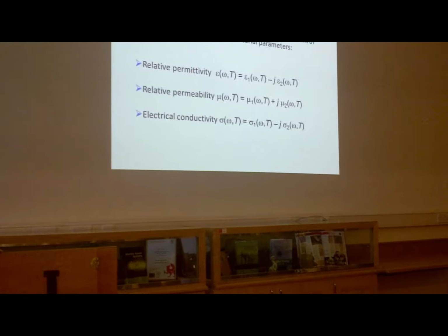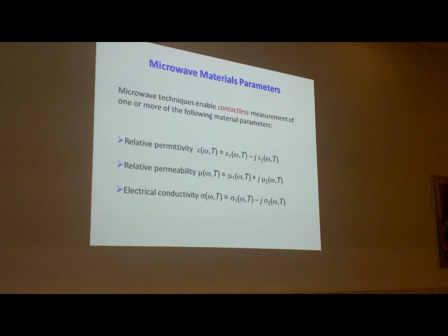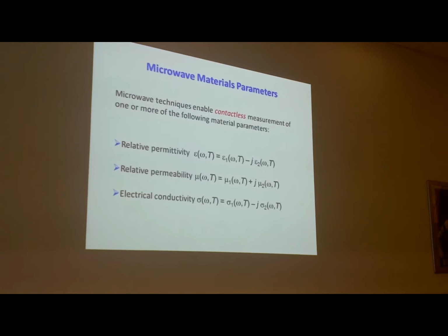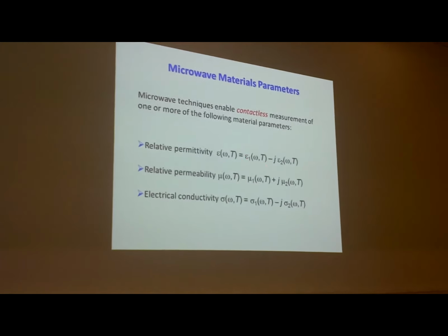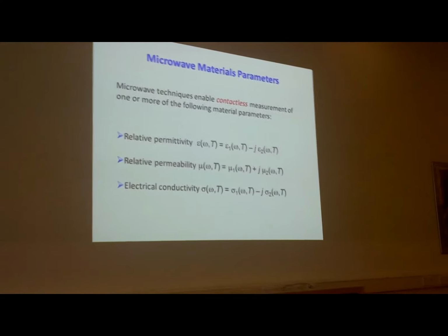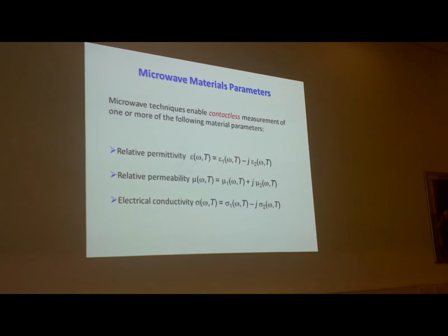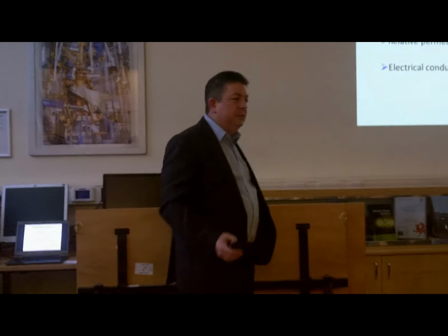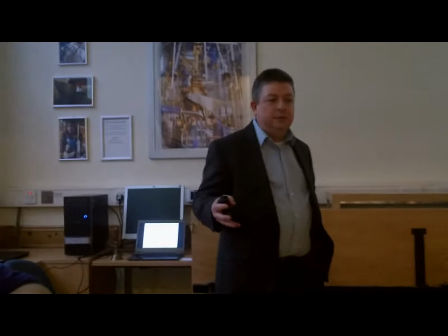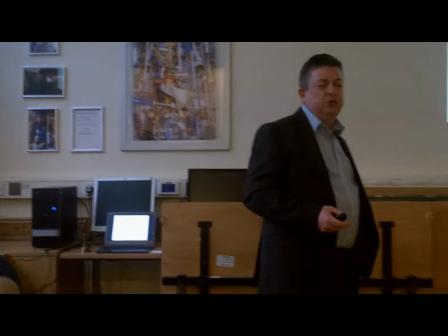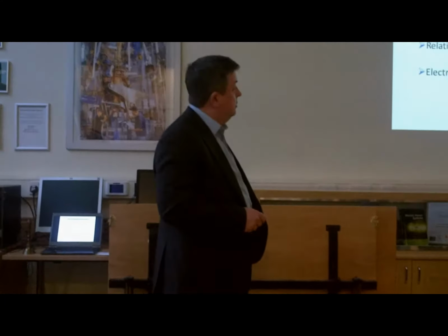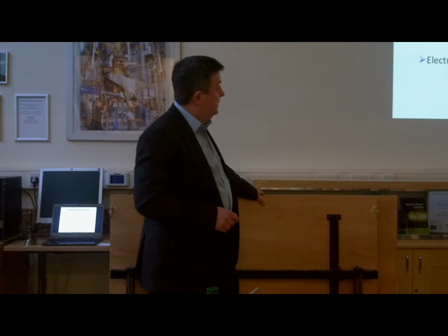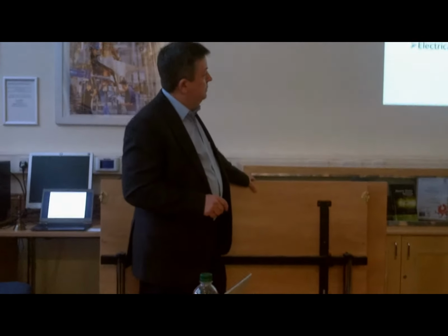Put conductivity down here because that's often folded in with permittivity, because conductivity is the response obviously due to an applied electric field. And these have real and imaginary parts, but what it means physically, of course, is that you've got a real bit which quantifies stored energy, and then an imaginary part which quantifies loss. So every time you polarize something, you store energy, but the response is also dissipative, so we can measure both parts of that, and hence get a lot of information about the system.